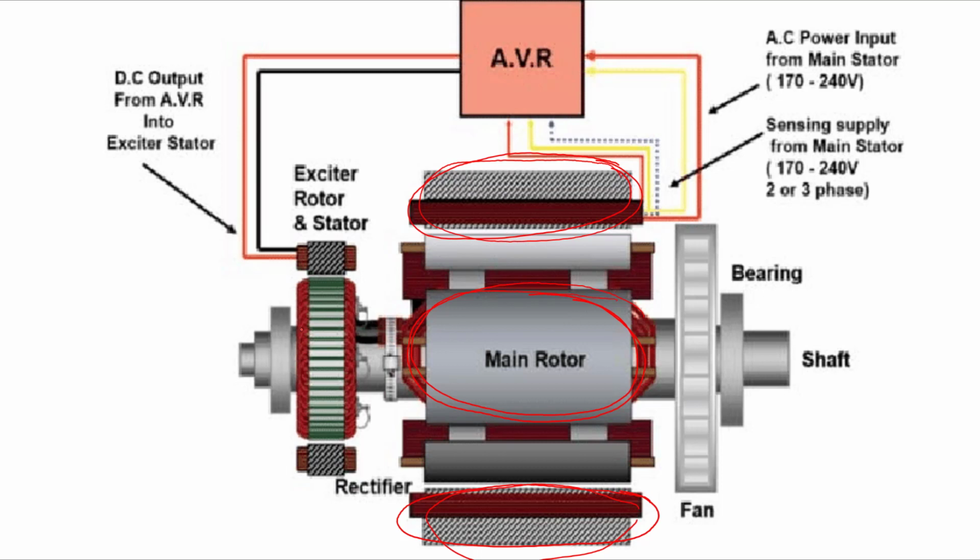So you can see here, this is your exciter system where we rectify and feed the DC to the field through these brass contacts. This is your slip ring and these are the two rectifier circuits. Through the rectifier circuit and the brass contacts, it feeds the field winding which is placed on the rotor of the machine, right?